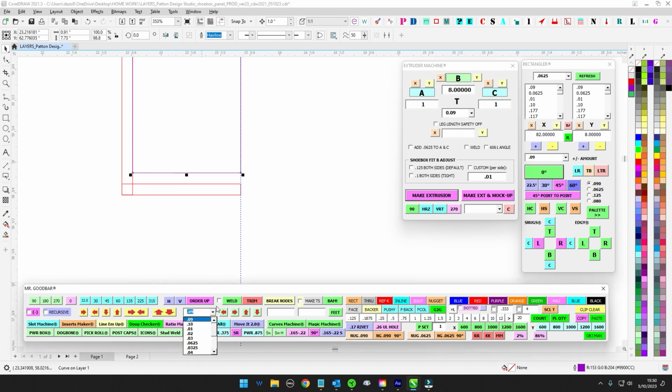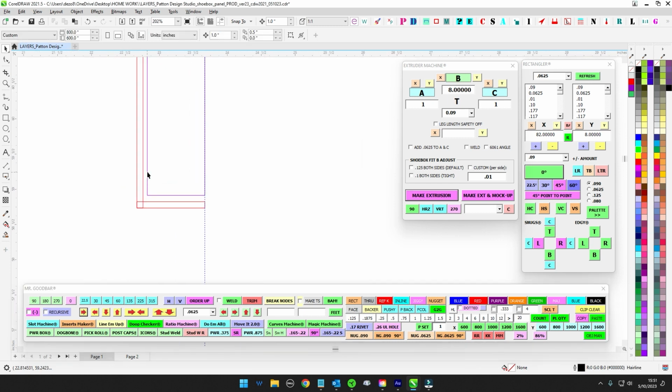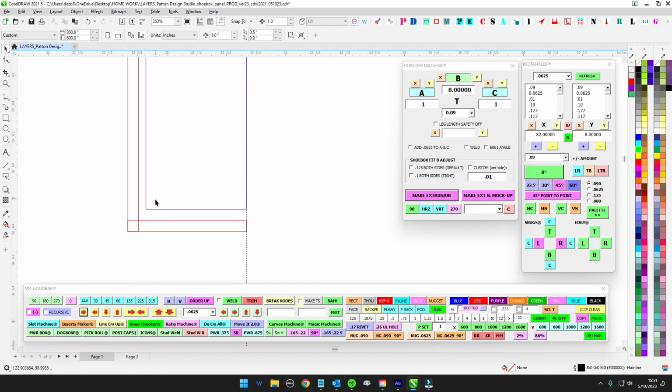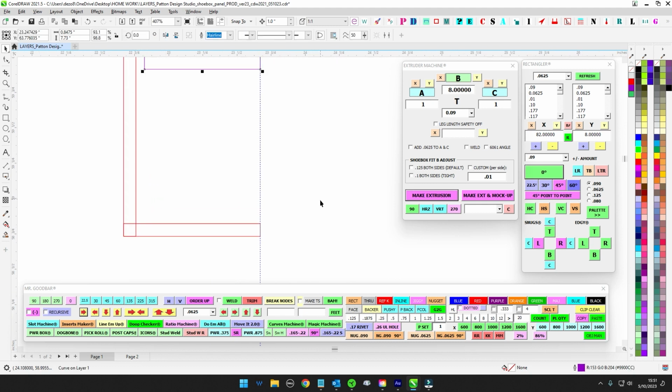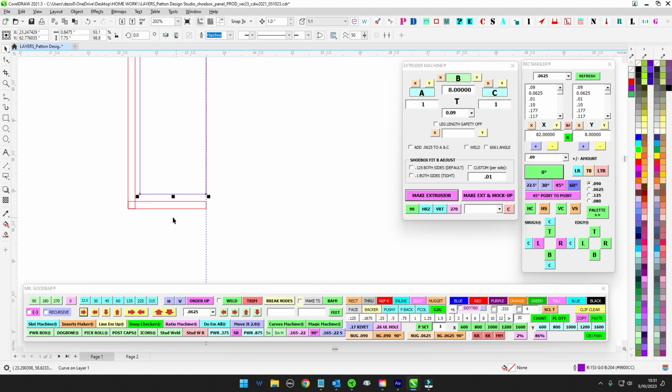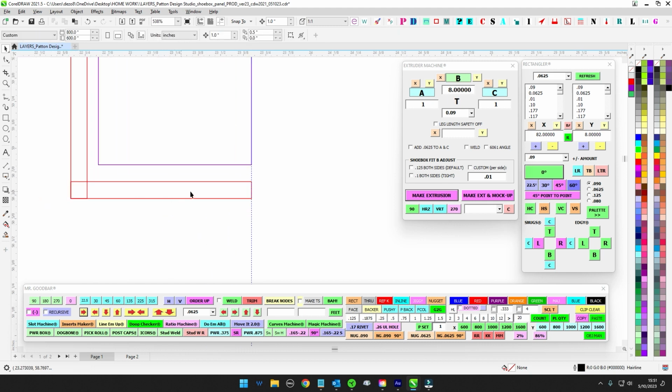What I'll do is oftentimes I'll just do a 1/16. And if we take it off the face, so you got the little arrow here, there you go. So now we have plenty of clearance on the front right here, so that way the backer piece won't interfere with the face. And that allows the face to snug all the way up against the backer here.